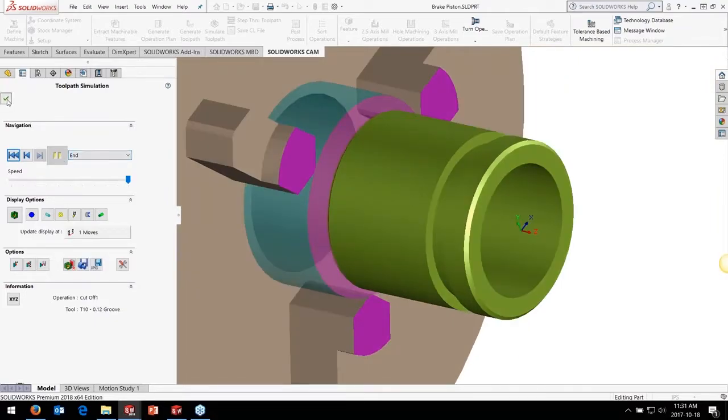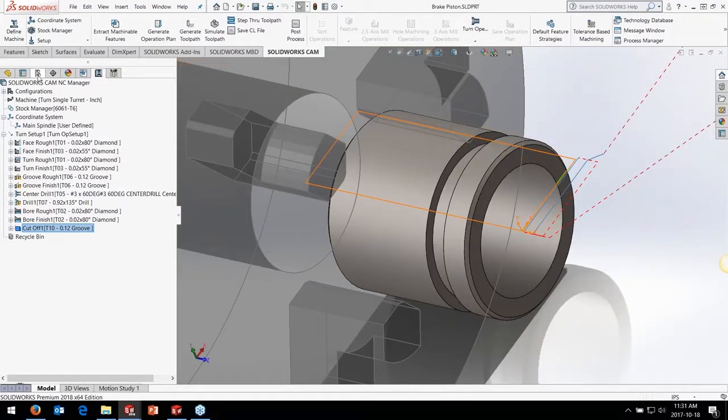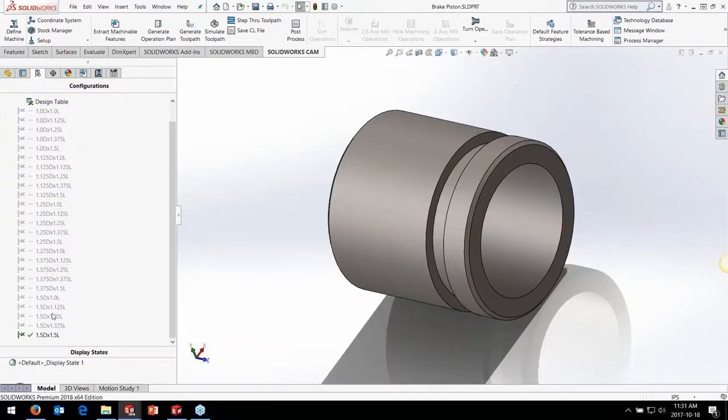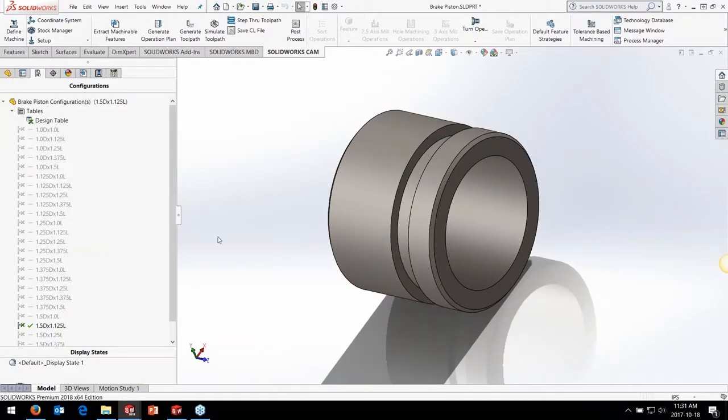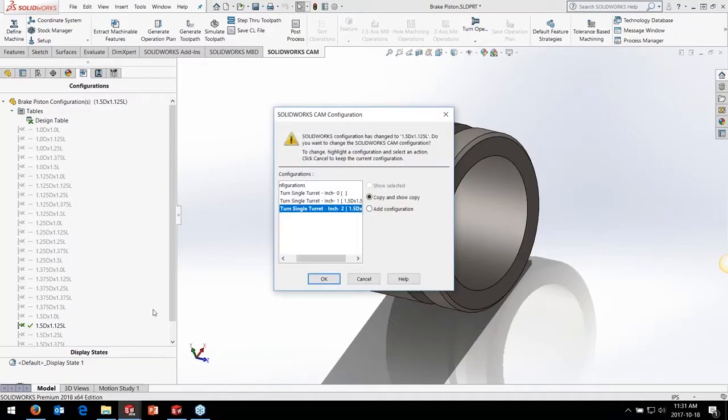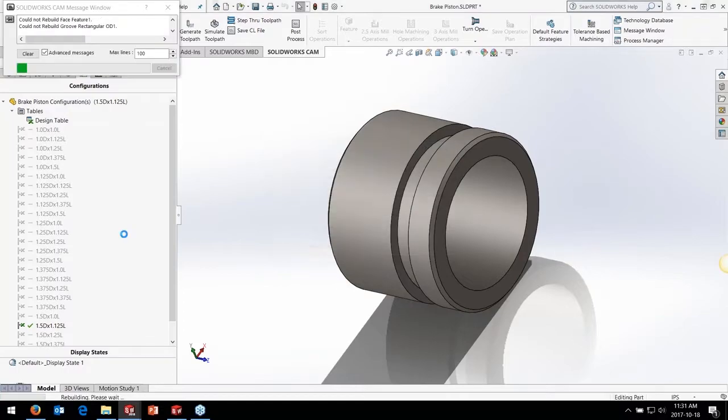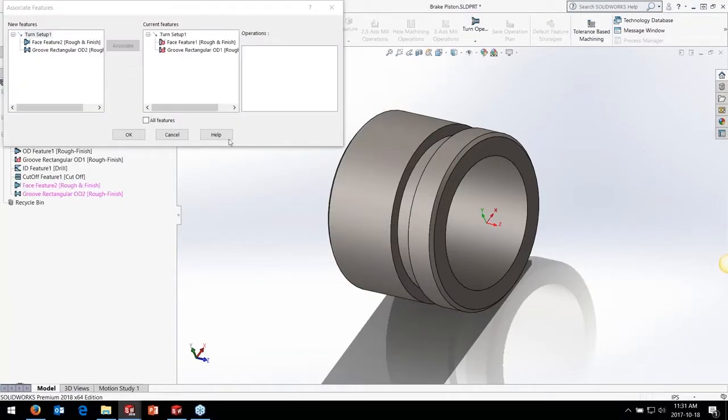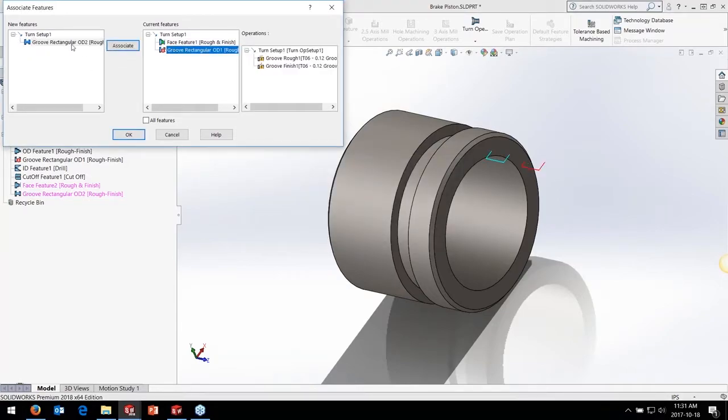And this is the great thing about the integration. Hey, you've got this feature, it found this one, do you want to sync them together? Yeah, I'll associate them. Replace, work together, these two, associate them, replace. Click OK. Now I've got my lathe program that I can just generate for this particular one, and I've got my toolpath updated for this particular part here for a shortened version. So I don't know of any other CAM program that can do things this quickly, which is some of the amazing things that SOLIDWORKS and CAMWorks have been doing for several years now.